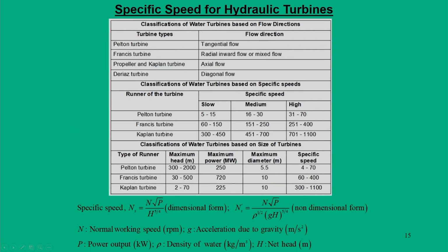In our last lectures I gave these slides with this particular table which talks about the class of turbines depending on the flow directions, and the class of turbines based on specific speeds. Now, we have more focus considering all types of turbines, and they fall in three categories: low, medium and high, and all turbines can also be useful in these three categories, and based on their specific natures they can be operated for maximum and minimum power, maximum diameters, and suitability of particular locations.